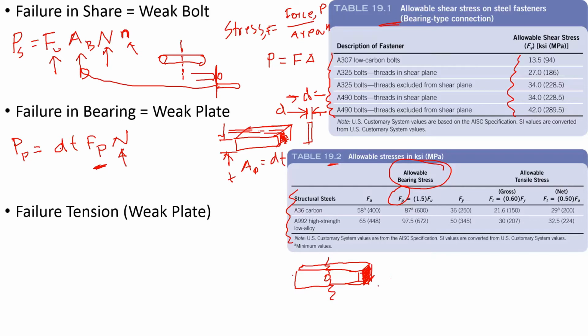Now for the projected area, you can calculate the gross area, meaning the total projected area, but in actuality you shouldn't be considering this hole, so you have to subtract that hole from this gross area. That is called the net area. So if we subtract the holes' area, you may have lots of holes, all holes subtracted from the gross area, you get the net area. So there are two equations used.